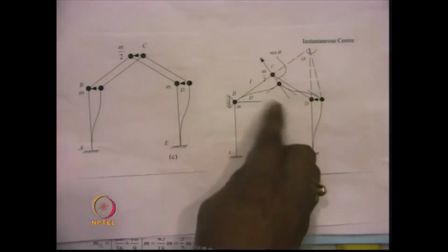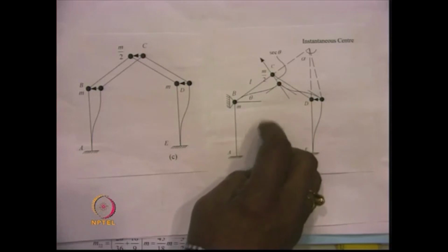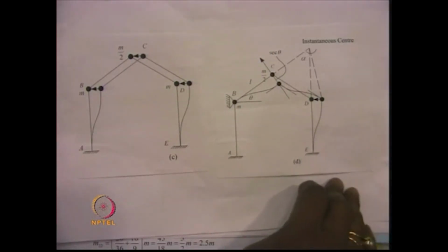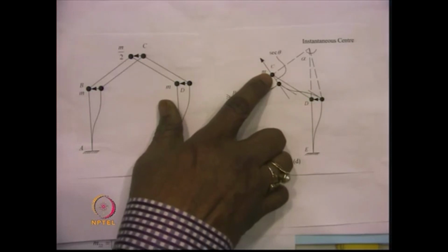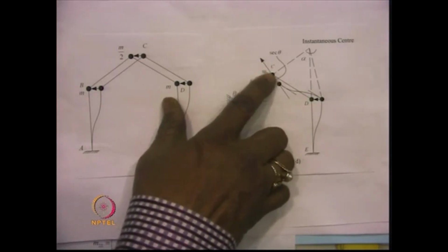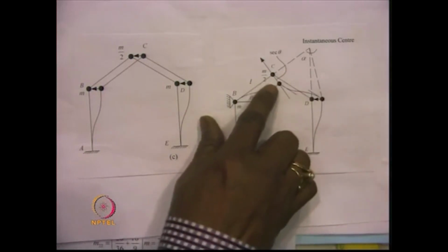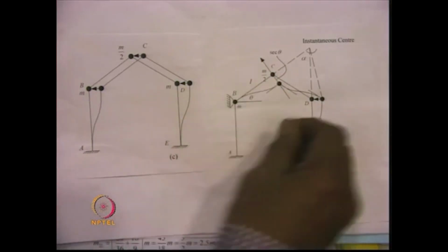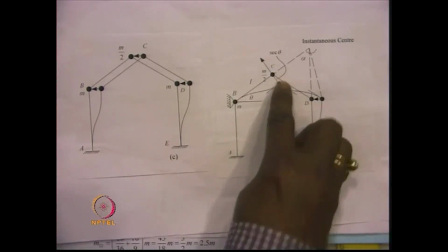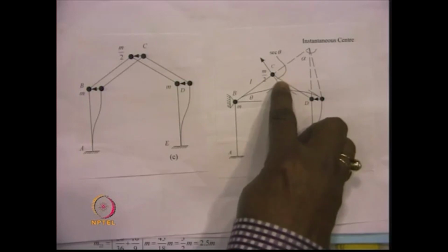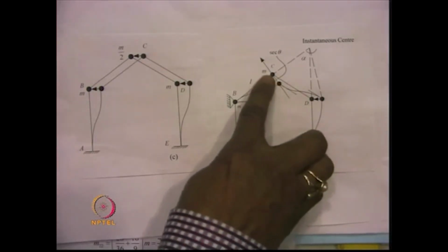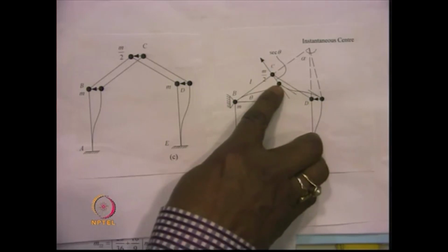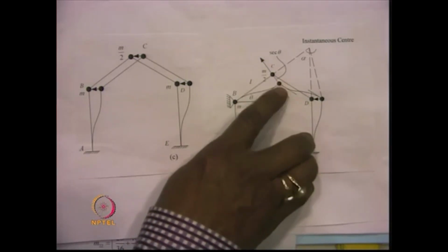So, thus by giving this kind of movement, we can ensure that the condition of inextensibility is satisfied. Now, this point not only moves vertically down, but also moves horizontally, or in other words, this point moves perpendicular to this. Now, one can find out that for a given displacement on this side, so that there is a unit acceleration produced in the vertical direction, we will have a component of that acceleration in this inclined direction, mass times, or m by 2 multiplied by that acceleration will be the force induced over here.